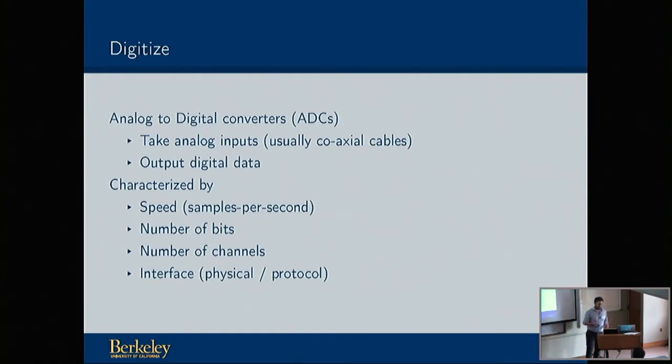Maybe you have a very, very large array, and this number could be in the hundreds or thousands. And of course, you need to plug the ADC into something, so there are interface requirements, both physical, what is the physical connector, that's going to mean you can plug this board into this board, and also what's the protocol, what does your ADC speak, how does it present data to your downstream processor, can your downstream processor read that data and interpret it in some kind of sane way.